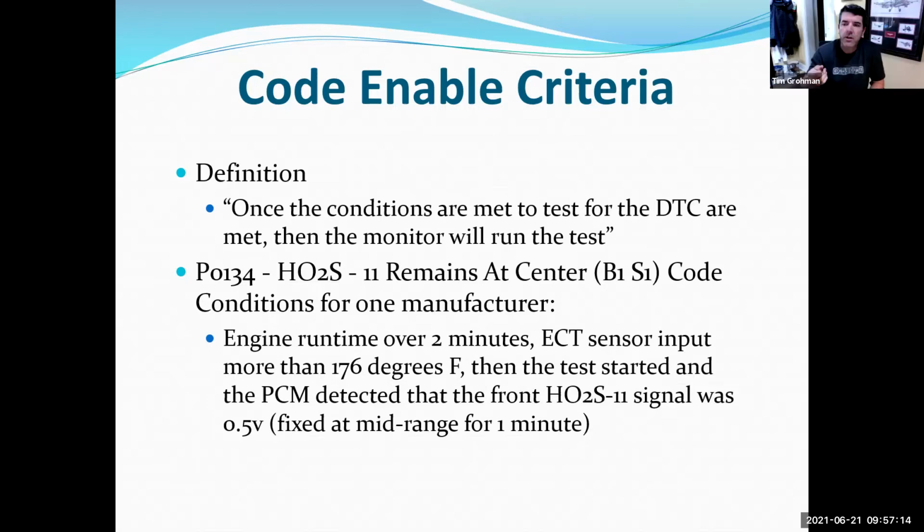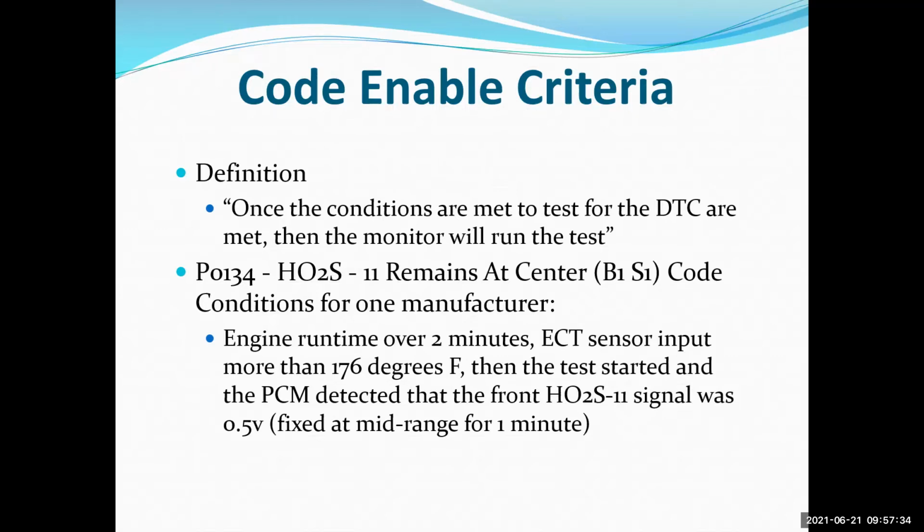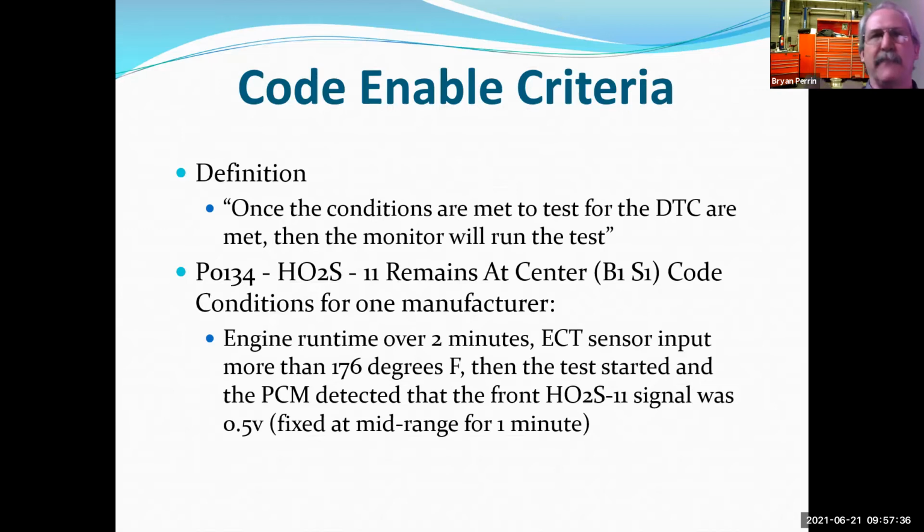And again, is this information usually included in the scan tool? No. You got to look it up somewhere else. Now, some scan tools like Snap-on have a troubleshooter function where they will give you some of this information for some codes. So that saves you another trip, which is really nice. Other scan tools don't have that. Some factory scan tools not only have it, but walk you through the whole diagnostic procedure. But those tend to be some very high-end European scan tools for European vehicles. So consequently, I'm going to All Data and looking this up.